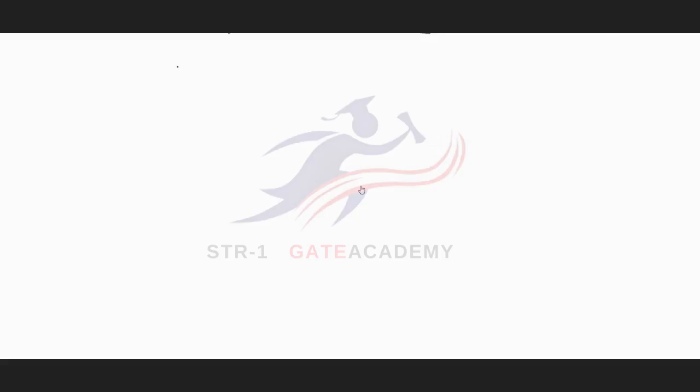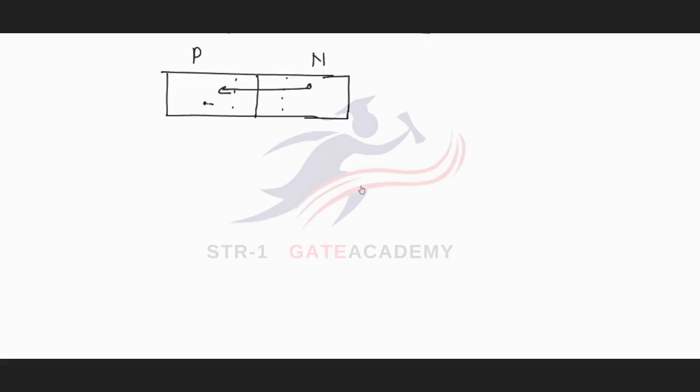Now, unlike in forward bias PN junction, there was no diffusion of charge carriers during the conduction. From N side, holes were crossing the junction, and from P side, electrons were crossing the junction. Here, the hole is moving from lower concentration to a region where hole concentration is very high. So this current cannot be a diffusion current, while this electron is moving from P side to N side into a region where electron concentration is already very high.